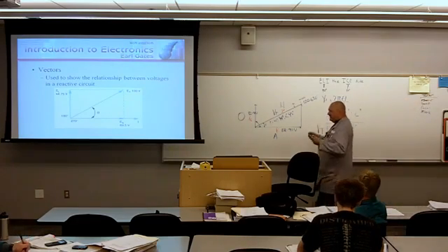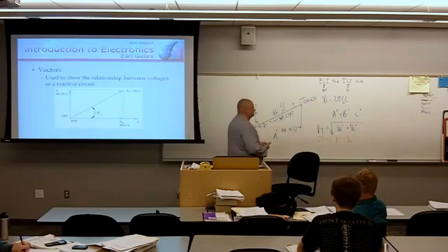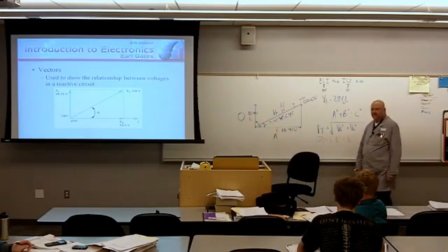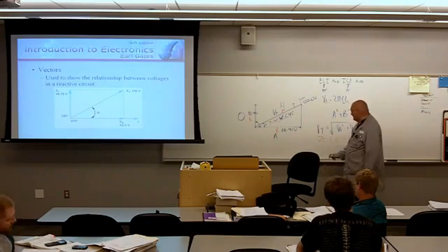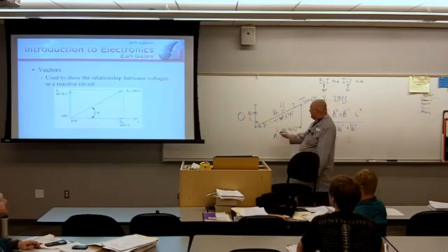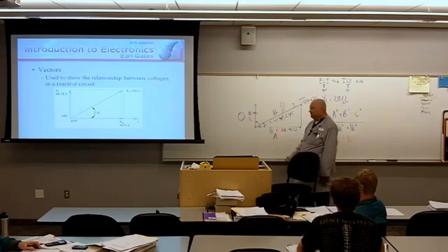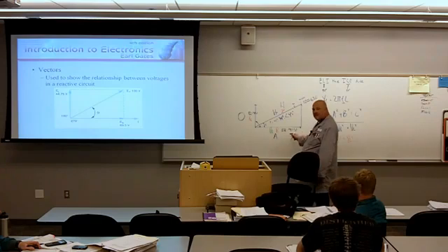What's something else that we could plot out this way? What else is additive in a series circuit? Power. Isn't power additive in a series circuit? That's actually a safe answer because power is also additive in a parallel circuit. So I could do the power of my resistor here, because obviously the bigger the resistor, the bigger the voltage drop, it's going to dissipate more power.